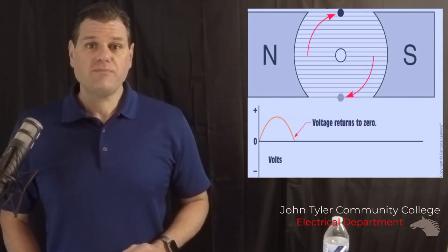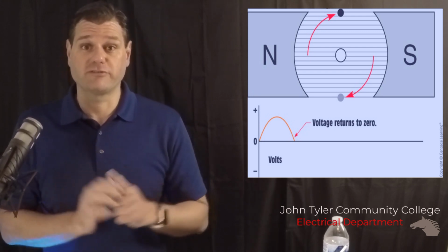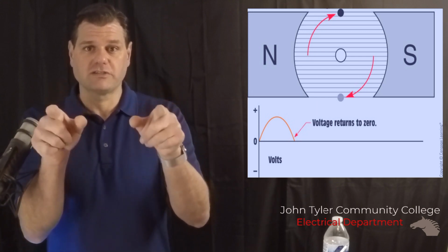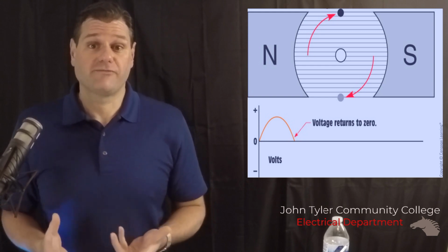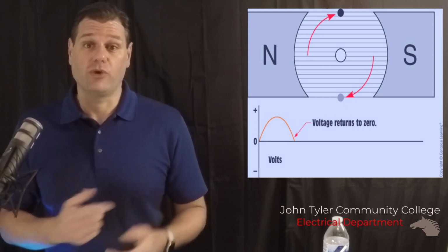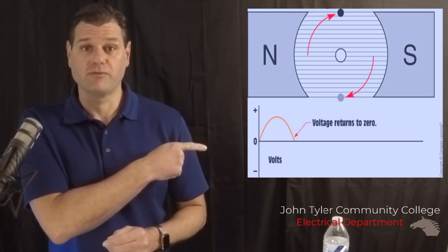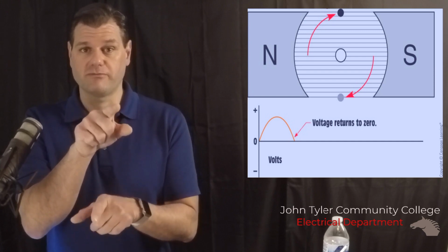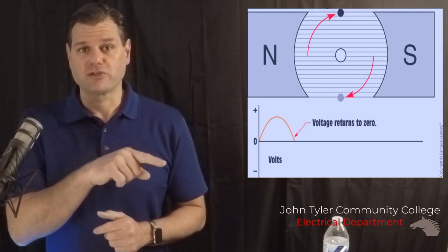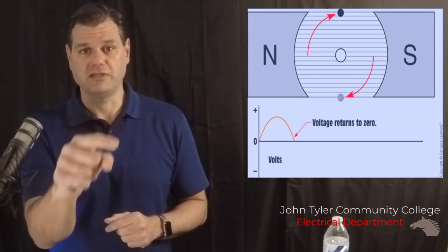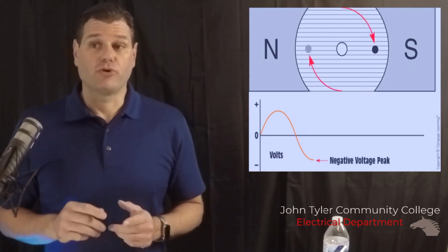We're going to rotate once again, and you're going to see that now we are 180 degrees from our original position, but only 90 degrees from our last position. So we were side to side, and now we are up and down again. We are currently outside of the flux lines, meaning that we are not cutting flux, and we are back again at 0. Okay, we are not in the same position because time has moved. From the time it took to rotate from the first position to the second to the third, time has been moving the whole time. So that's why we get this increase to a max, and then decrease, and then back to 0.